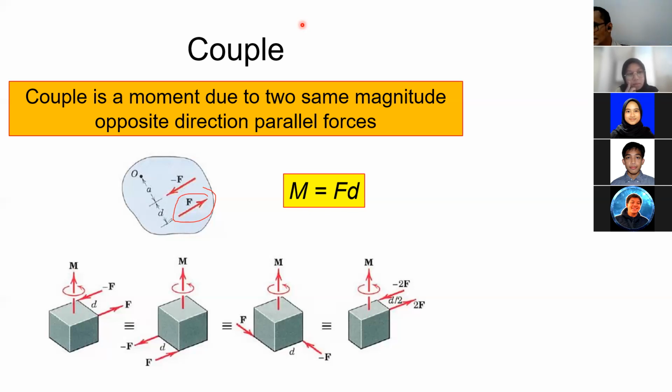What is the magnitude of the force? F, right? Okay, and what is the distance between O and F? Do we need to add A and B? Yes, of course. A plus B. That's the moment due to F, right? And the moment is counterclockwise, right, Fatima? Yeah, counterclockwise, like this.